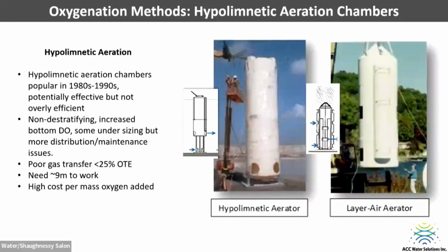Oh, next one. So hypolimnetic aeration. The idea behind hypolimnetic aeration is it's kind of a cross. It's a little bit of oxygenation and aeration. There are different models out there, but basically the system is designed to suck water from the bottom of a water body, bring it up to the surface where it either interacts with atmospheric air or you expose it to pure oxygen, and then you bring it back down to the bottom without disturbing the sediments.